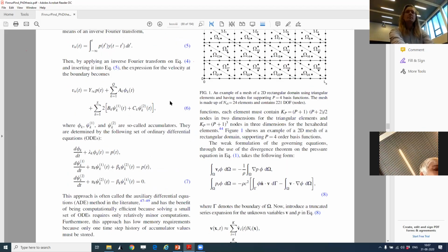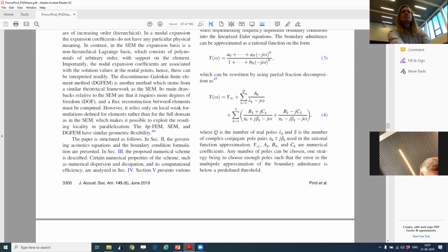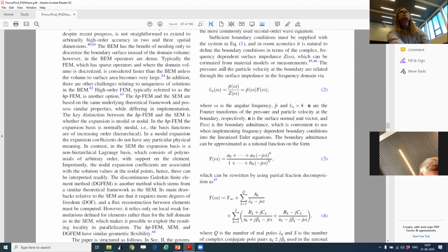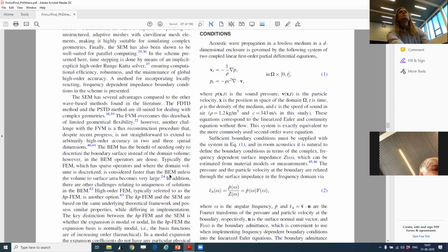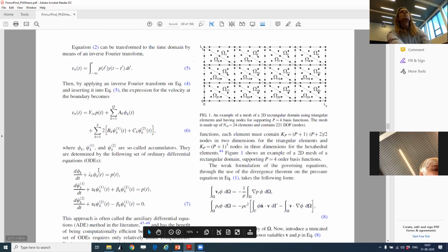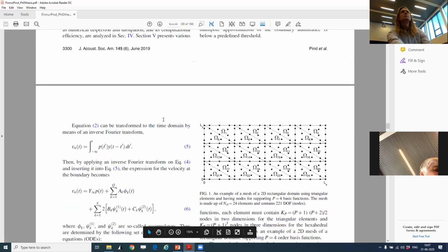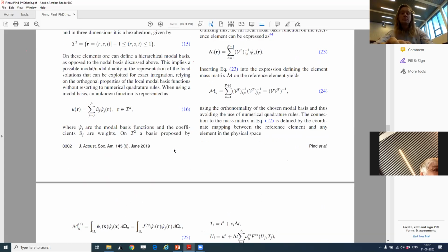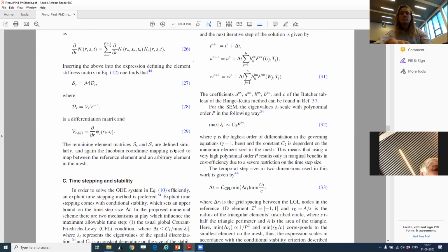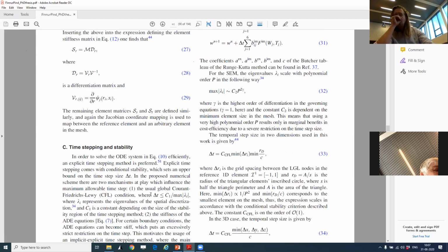we're solving two systems, one can say. We're solving the main system, which is this system here, and then we're solving this auxiliary system, which is the boundary conditions, right? And for the stability criterion, we need a certain time step, as is described here in the discussion on the stability, we need to have a maximum time step in order to preserve the stability of the simulation.